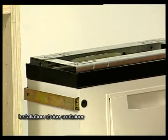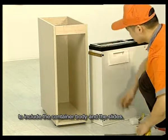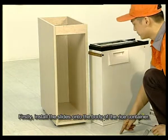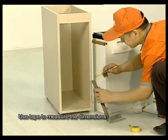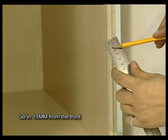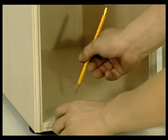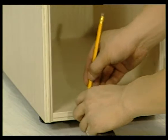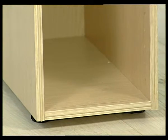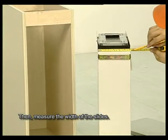Installation of rice container. The rice container consists of two parts: the container body and the slides. Firstly, install the slides onto the body of the rice container. Use tape to measure the dimensions of the bottom panel of the rice container. Go in 15 mm from the front and mark the line on the bottom panel. Then measure the width of the slides.